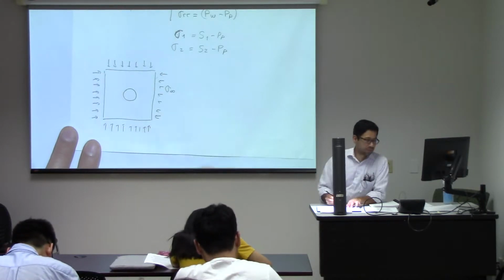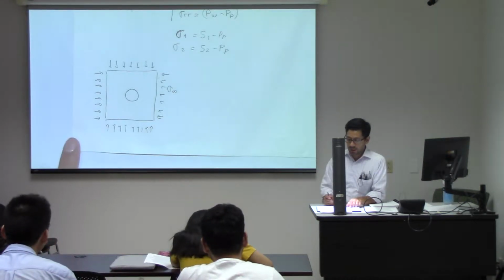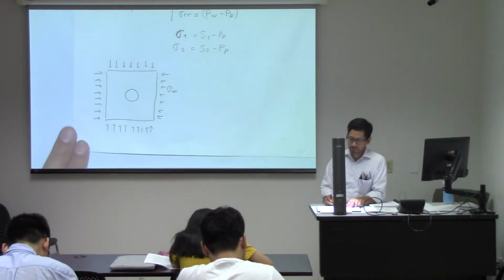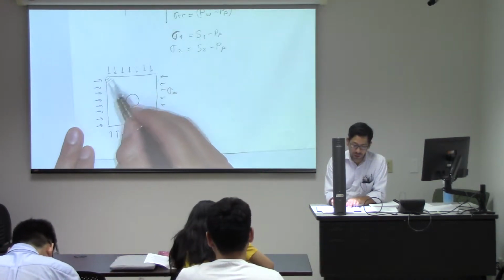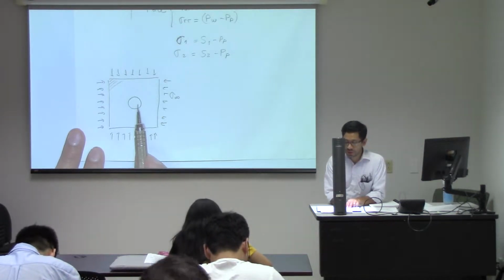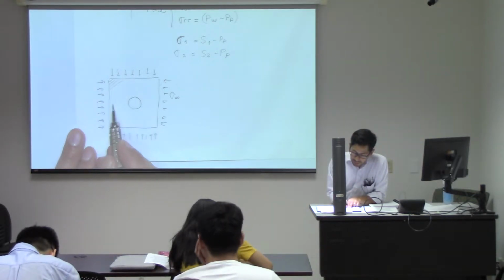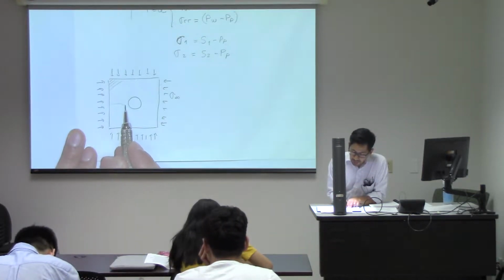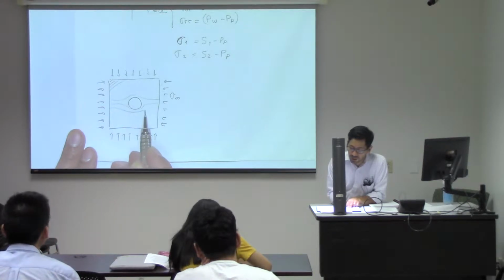If you were to solve the equations in Cartesian coordinates, you will see that, if this is rock, or a solid, and here there is nothing, do you think the stresses can travel through nothing? No, right? So you will see that these stresses, in order to go around the cavity, have to sort of bend around the cavity, very similar to flow lines of fluid flow.